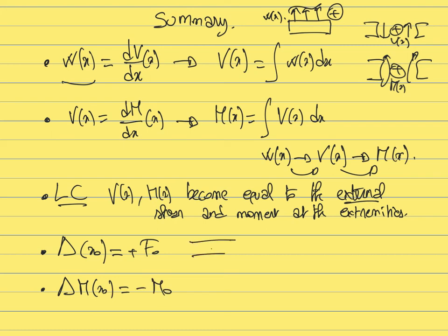So that's a case where you have a concentrated shear force like this at a point x naught, or when you have a concentrated moment at x naught like this, that is going to induce a discontinuity in the internal shear or the internal moment. So those three relationships, the limit condition and the discontinuities, will allow you to find the integration constants that you will need to get when you integrate the load.